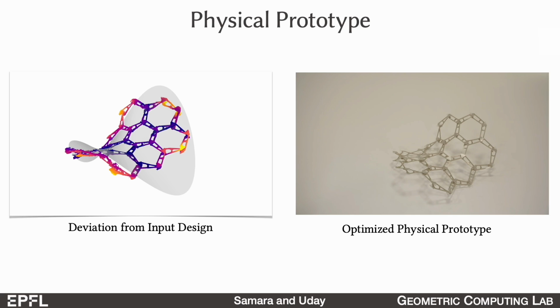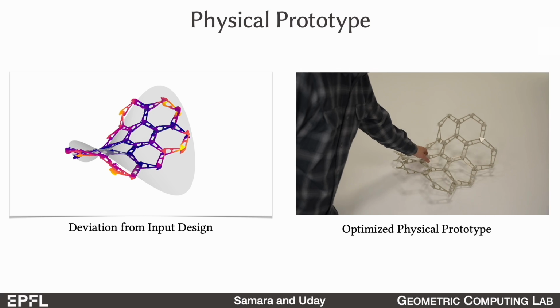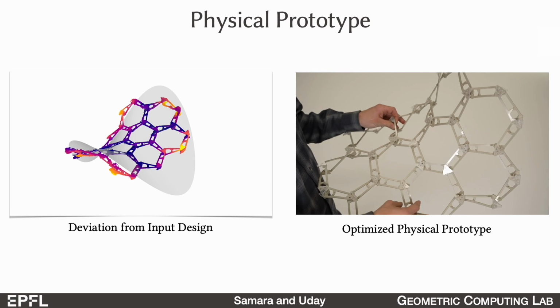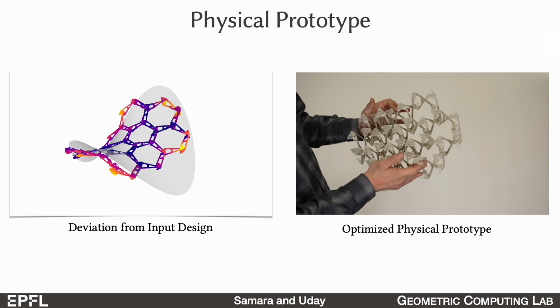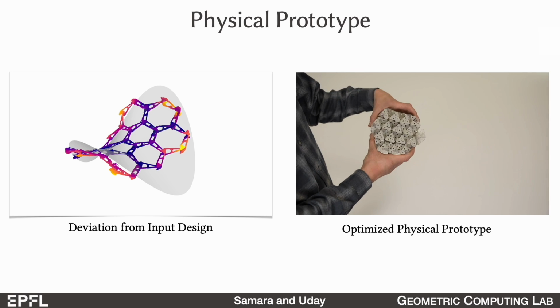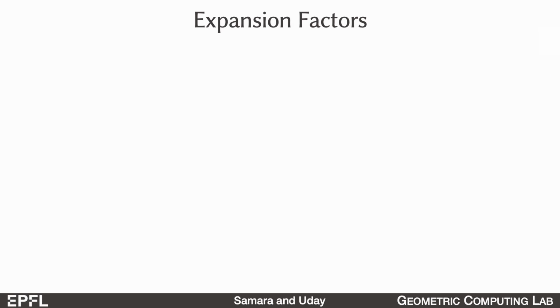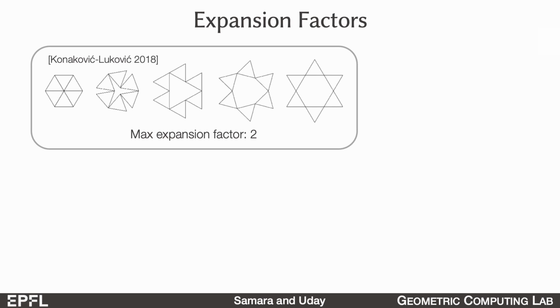The average deviation is about 1.3% bounding box diagonal for this model. Here you see that the saddle is bistable. It doesn't need any external forces to maintain the deployed shape, and we can undeploy it again by forcing some units to open. The conformal initialization part of umbrella meshes is very similar to a previous deployable auxetic material.